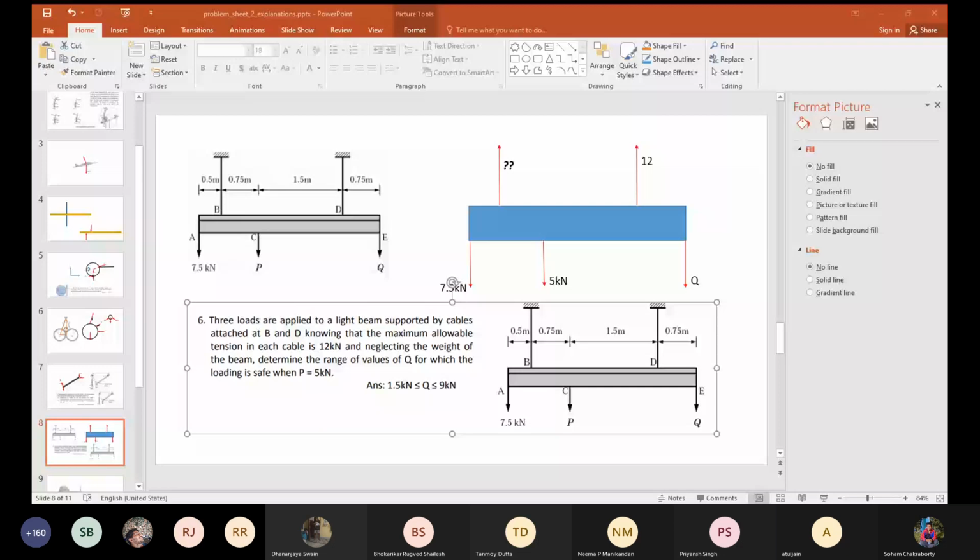So I have a question which is actually related to 7, but not strictly related to the problem itself. Tell me. So are the actual trusses in real life also designed keeping in view of these maximum stresses that they can handle, like the bridges and all? Yes, when you design a truss, when you design a bridge, you have to think about several things. One is the reaction of the supports. Your support should not collapse. But most critical usually are the pins which are joining the different members. They are most likely to fail. So you have to make sure that those are thick enough.